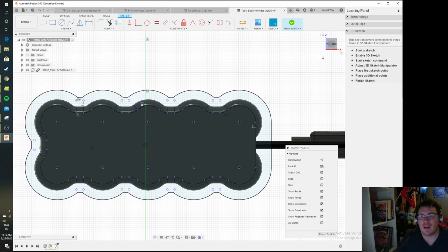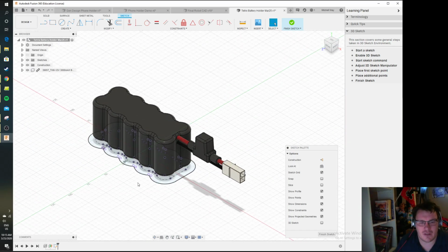Press OK, and what you'll notice is that everything got highlighted a little bit green there. That's important because if I go back to my drawing, you'll notice that this, if I float over it, has now created an actual shape. And this is one that my students always fight with, is the difference between lines and shapes. Once you enclose a shape within lines, it will actually highlight like this. If you have left any of those lines basically unattached or unconnected, it will not create the shape.